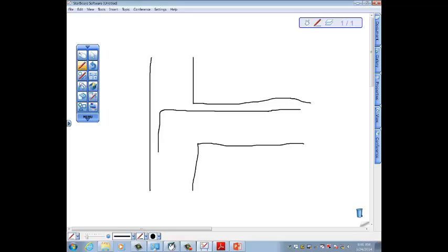Now, while you're drawing that already, it says refer to figure 13.2.3, which is what you were talking about, the diameter of the hook. So a 90-degree hook for a number 9 bar, I'm looking on page 546, is 9.5 inches. So that's what you were referring to, right? A minute ago? So that's your circle here, and I drew that wrong, so I'm going to undo that. Should be a 9.5 inch radius.